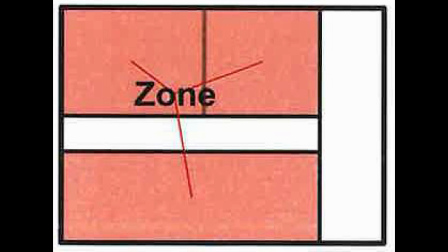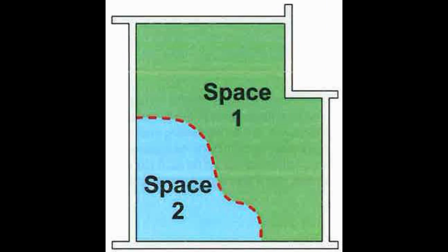Section 2. How spaces work. A space isn't created by drawing walls, it's placed into an enclosed region of the model. Revit automatically detects the bounding elements around it: walls, floors, ceilings, roofs, columns, curtain systems, and separation lines. If you imagine pouring water into a room, the water would spread until it hits a boundary. That's exactly how Revit defines a space.